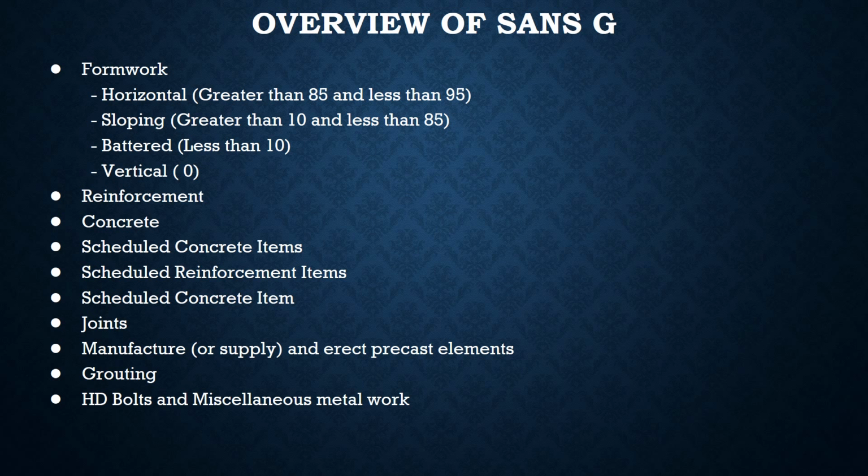Each steel section or mesh is measured separately. However, no allowance is made for cutting, waste, laps, spacer devices, or binding wire. The rates include supply, cutting, bending, placing in position, and fixing in position, including spacer devices and the binding wire.